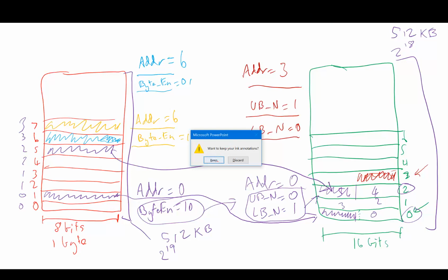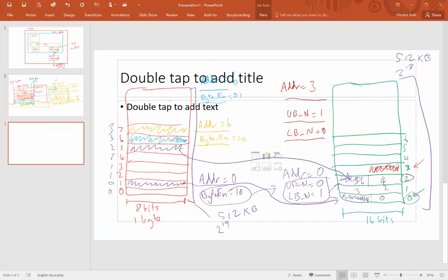All right, so I think that's everything I wanted to cover to explain the SRAM, the part 2. So in order for you to test out that the SRAM is working, the assembly code is going to be very similar to the first part. However, now every single address in the address space has a unique location in the SRAM chip. So you probably want to do a write and a read from every address, which you can just do in a loop.